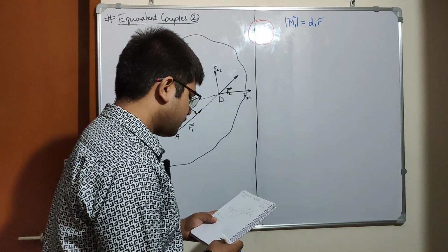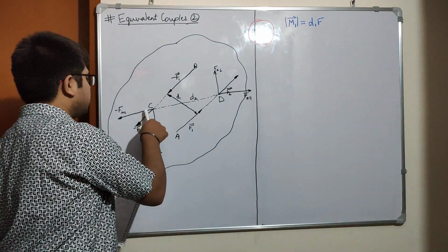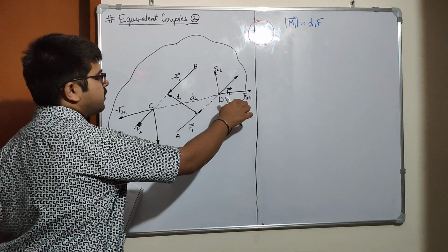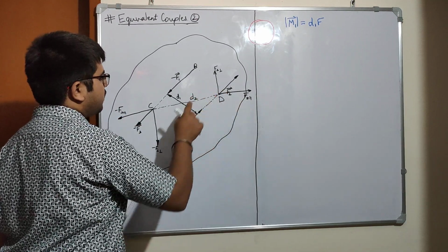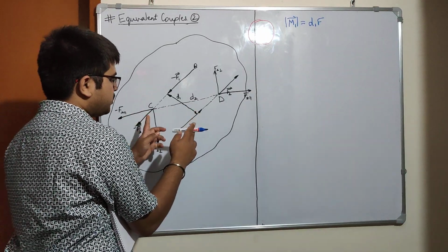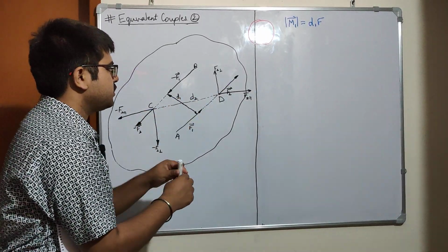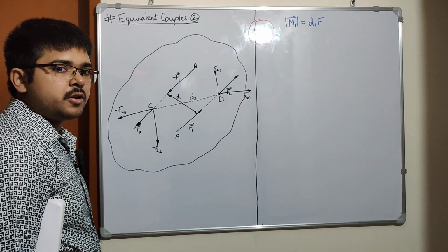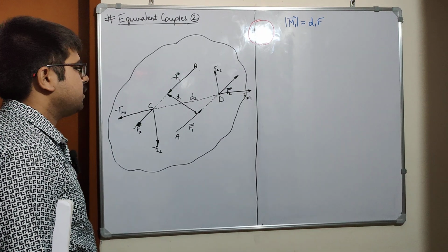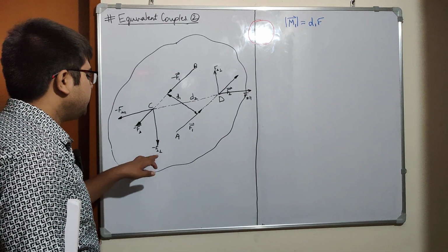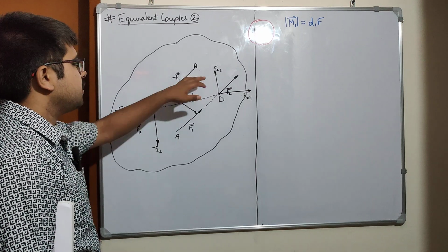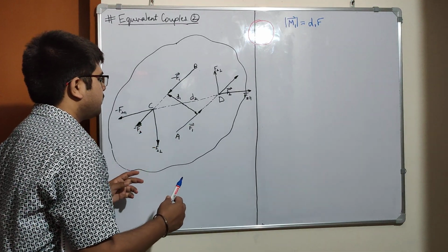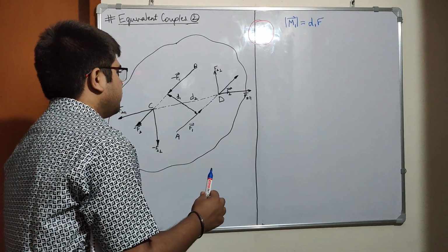And if we see here, this vector minus F2 parallel and F2 parallel will have the same direction, along this direction and along this direction. So these will not contribute to the moment for the rigid body. Only minus F2 perpendicular and F2 perpendicular will have a moment that will cause the body to rotate.